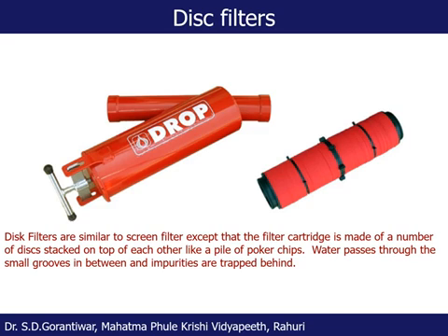So those are mounted like stacks of discs with each other, and water passes through the small grooves in between and impurities are trapped behind it. What happens here, you see the filter element with a number of discs actually. Each disc has small grooves.